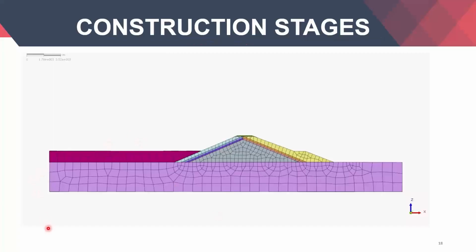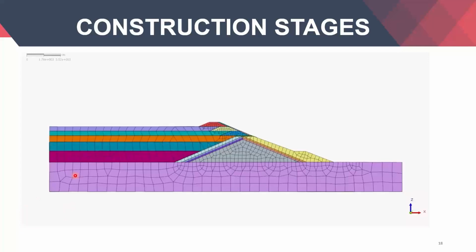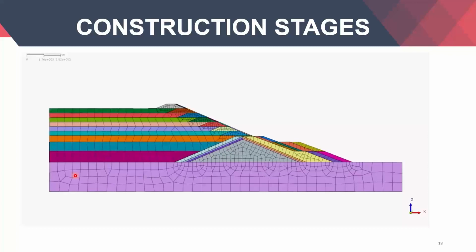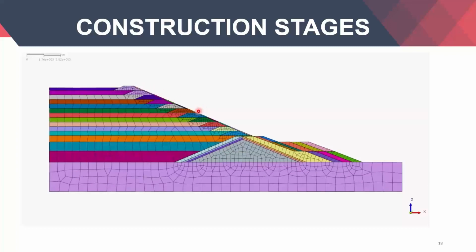So I'll play a small animation of the construction stages, then I'll define you what it exactly looks like. So you can see with each deposition, the raisings have been done along with the rockfill support. And after this sixth raising, we start creating the buttresses so as to ensure that we can check on the factor of safety, or we need to stabilize the dikes.